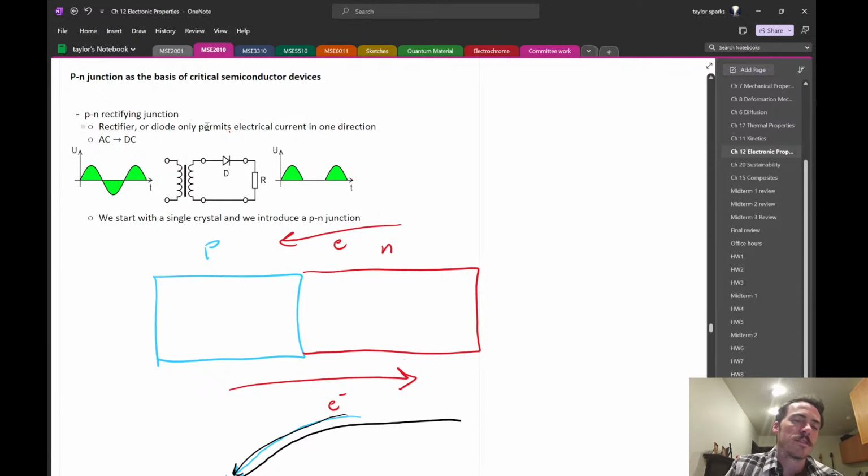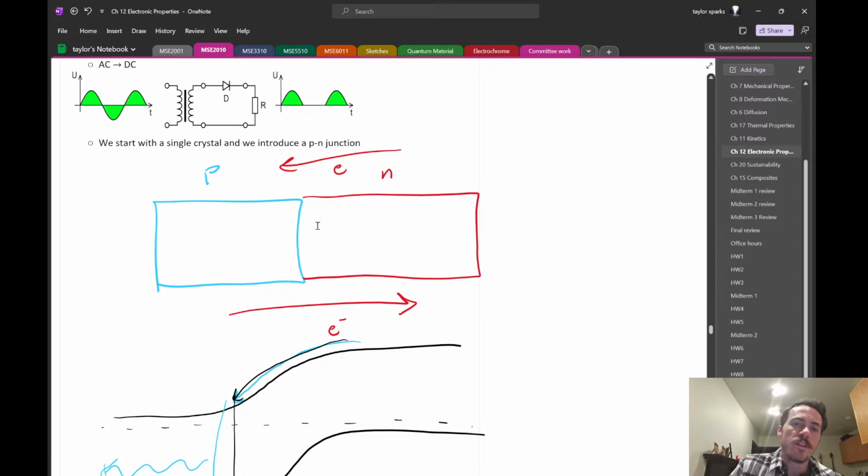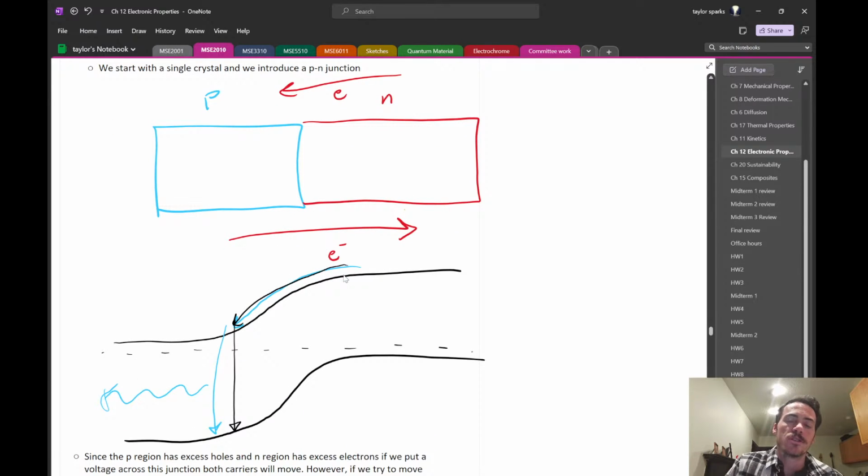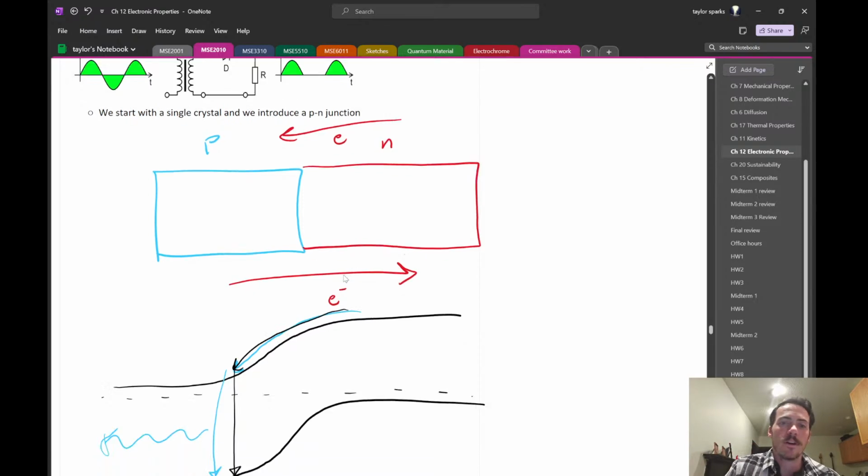I'll just go through this. Like, what is a rectifying junction? It takes an AC signal and turns it into a DC signal by chopping out either the positive or the negative part. It does that by basically saying when the holes and electrons travel away from this junction, you get just regular current. But when they travel into that junction, you get recombination. That's an example of understanding how a PN junction works to form a rectifying junction.